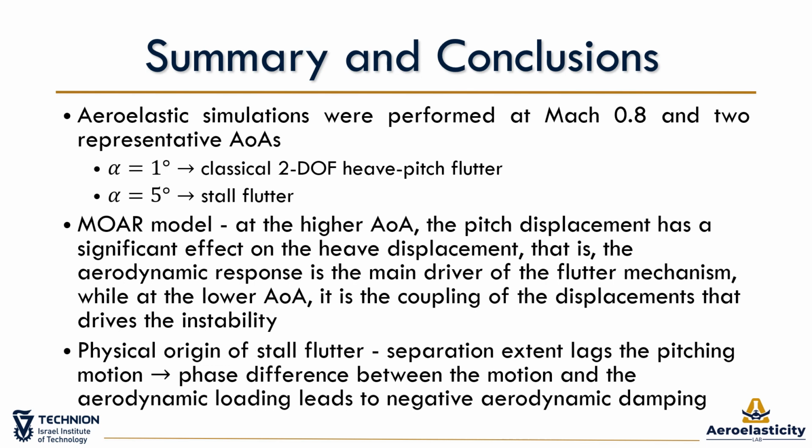Analysis of the flow separation on the BSCW at the higher angle of attack revealed that the separation extent lags the pitching motion, leading to a phase difference between the motion and the aerodynamic loading, and consequently to negative aerodynamic damping that drives the stall flutter mechanism.